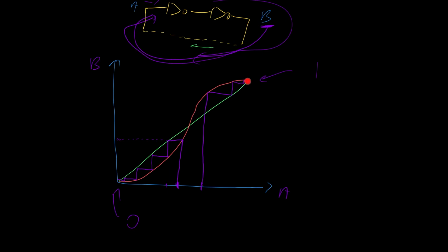This rigorously allows us to see that even if we have some noise perturbation, then this circuit will push us back to a logic 1 or push us back to a logic 0. And I drew this to be smoother, remember. Normally we have a very sharp transition, and so you almost immediately go to a 0, almost immediately go to a 1. The middle here is the opposite of stable.